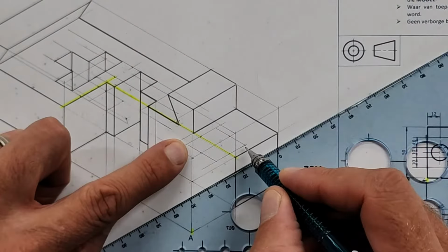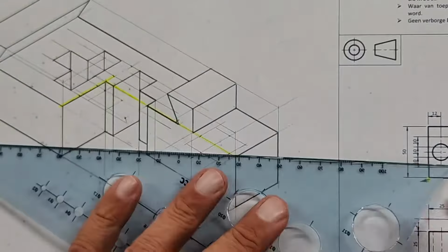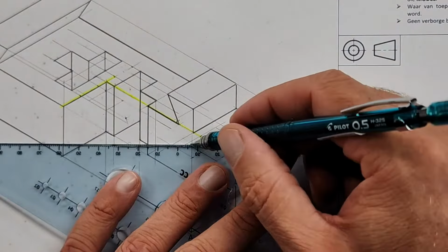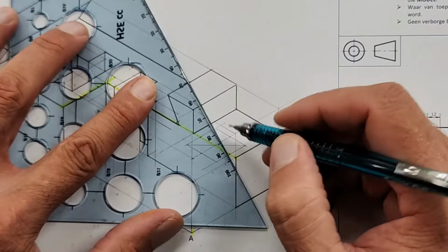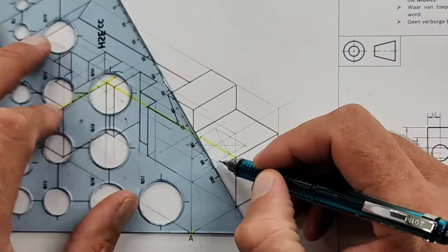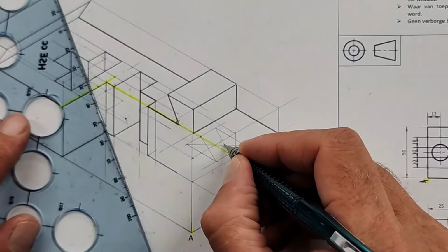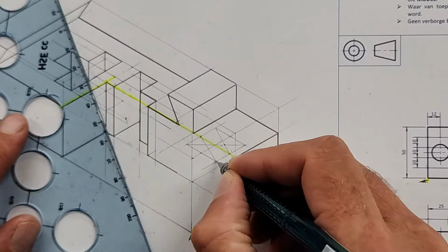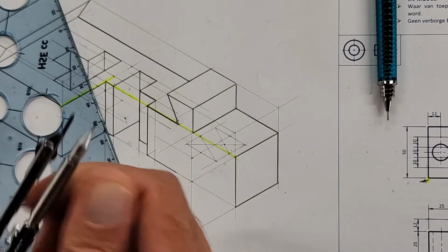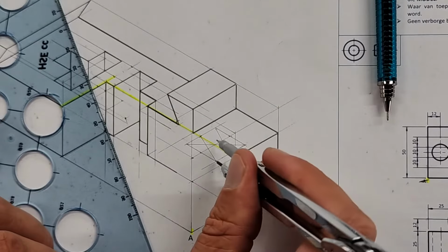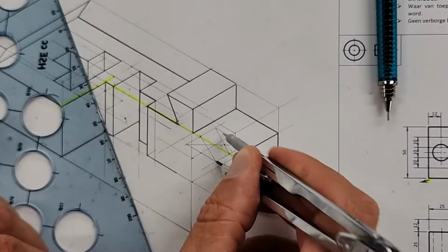Okay, so there's my isometric square for my circle. Same rules apply. Longest possible line. Then from the obtuse to the opposite. From this obtuse to the opposite. And this then is the center for that arc, and this is the center for that arc. So make sure your compass is nice and ready for it, because you just have to do half. From here to here.